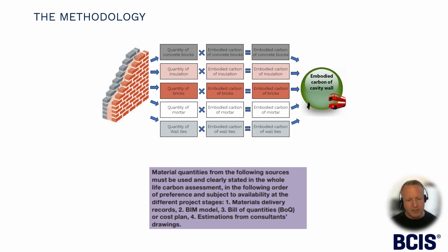So if you think something like a BIM model may not have split down all of the various components, it might just be almost a line indicating that it's a cavity wall. So there could be quite a bit of work that you need to do to understand the typical quantities of the blocks and the insulation and wall ties and other things like that. Of course, wouldn't be modelled.